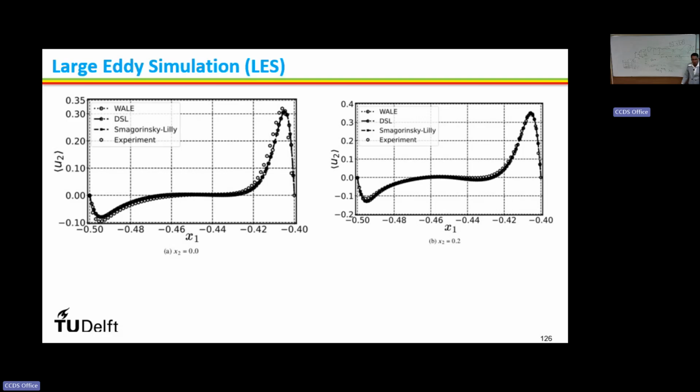We are using a scheme that gives respect to the direction of the flow, right? So in normal laminar or RANS simulation, we use some kind of upwinding scheme. There are different upwinding schemes: first order upwind, second order upwind, third order MUSCL, QUICK, quadratic upwinding. You might have studied these in CFD, right? But the issue with